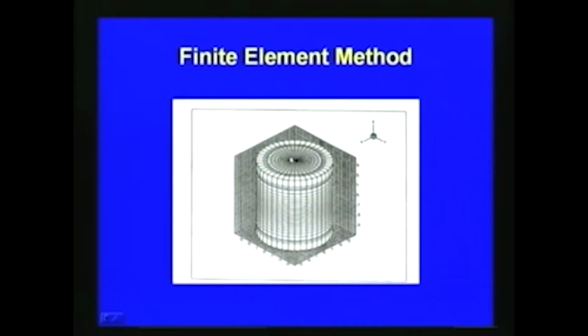For example, if in this domain there is a cylinder, and you want to see the movement of a sphere inside the cylinder, what we can do is discretize the domain in 3 dimensions like this, and then solve the 3-dimensional Navier-Stokes equation. We can initially transform the partial differential equation, the Navier-Stokes equation, into an algebraic set of equations, then apply the boundary conditions and solve the system of equations to get the unknowns. This is the essential principle behind the finite element method.